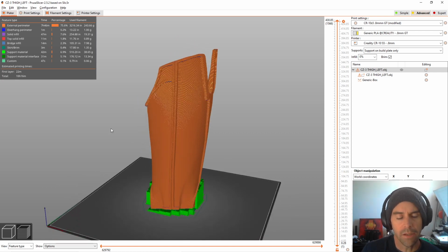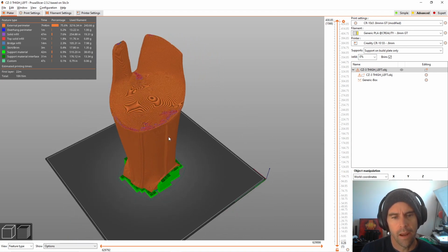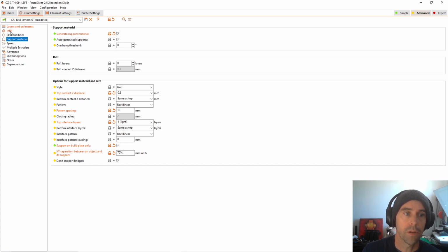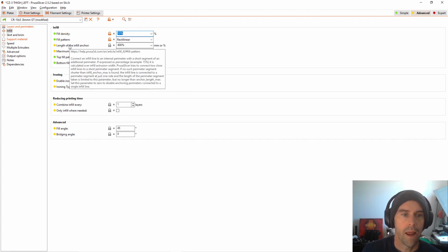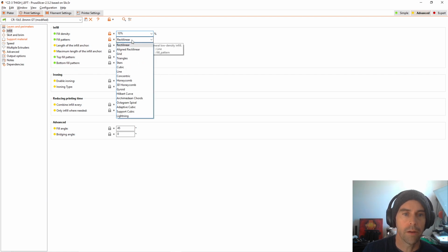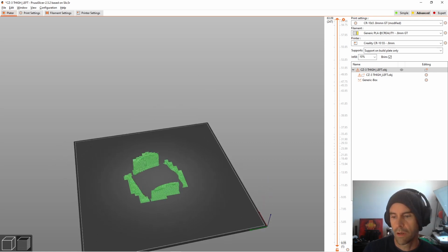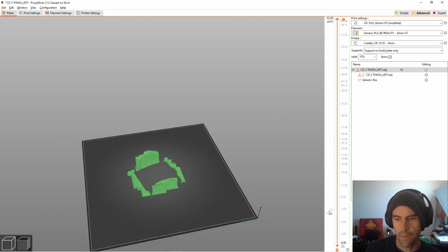Oh yeah, let's go back and look. So what did I mention before? The support material spacing. I think I talked about that. Oh yeah, the overhangs. So we go to print settings. Not support material, I'm sorry, infill settings. You don't need a lot most of the time. I'm going to do 10%, and then under fill pattern, go to the lightning, and let me see if this works. This might take a second to slice here. We'll see what it does. Did I even hit it? Is it slicing? There it goes.